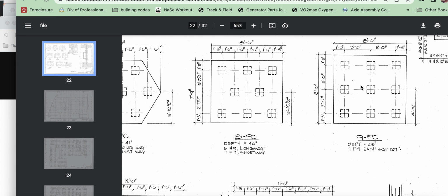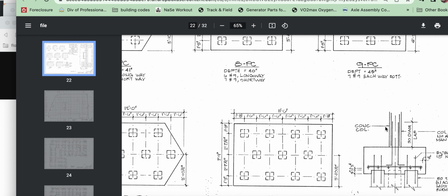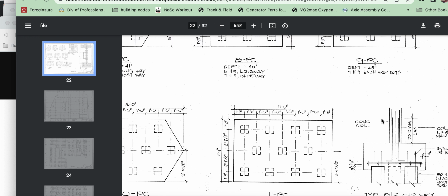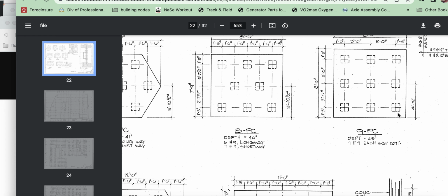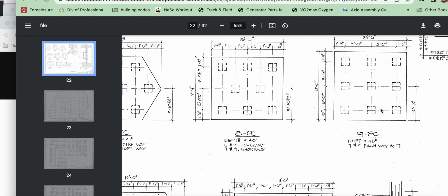But it's single point loaded from the column, and then the pile cap right here is distributing across all 9 points at the same, well, theoretically, with the rebar locking it in, it would be distributing across all 9. So 50, 50, 50, 150, 300, 450 tons.